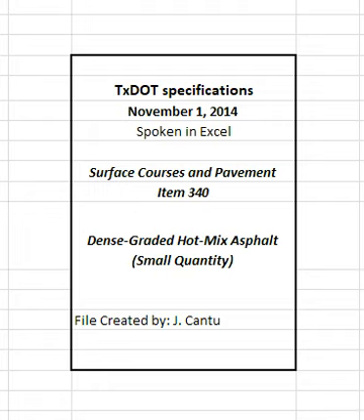2.1.2 Intermediate aggregate. Aggregates not meeting the definition of coarse or fine aggregate will be defined as intermediate aggregate. Supply intermediate aggregates, when used, that are free from organic impurities. The engineer may test the intermediate aggregate in accordance with TEX 408A to verify the material is free from organic impurities. Supply intermediate aggregate from coarse aggregate sources, when used, that meet the requirements shown in Table 1 unless otherwise